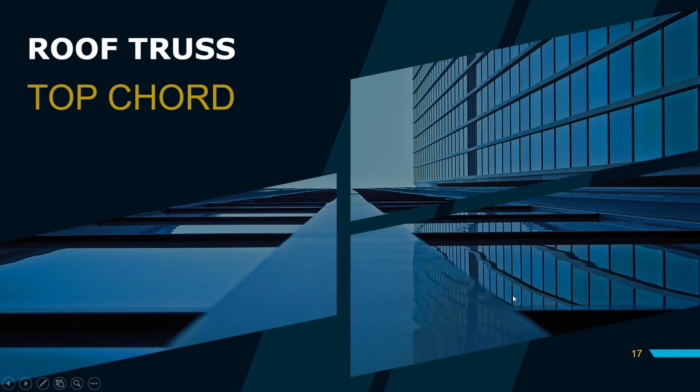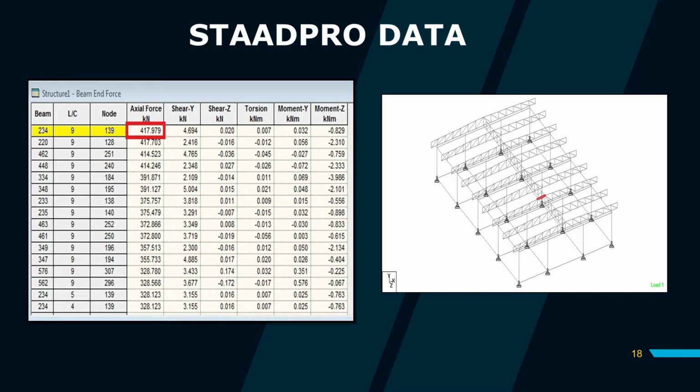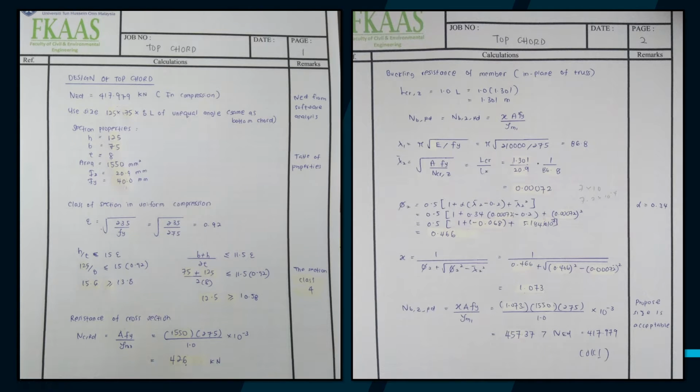So we go to the roof truss top chord calculation. So this is STAAD Pro data. This is the critical member, beam 234 in the top chord. The axial force in kilonewton is 417.979. So we go to the calculation of the top chord.